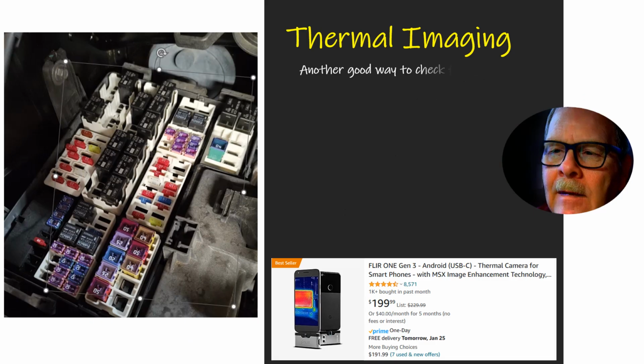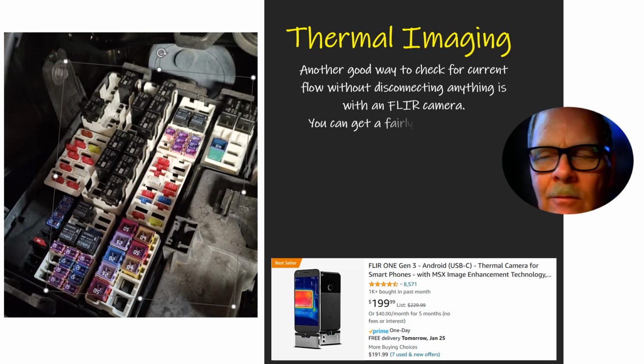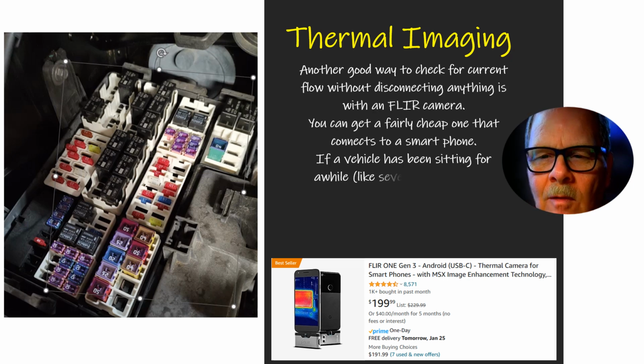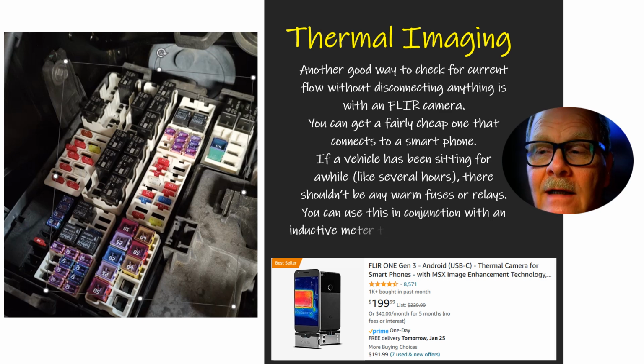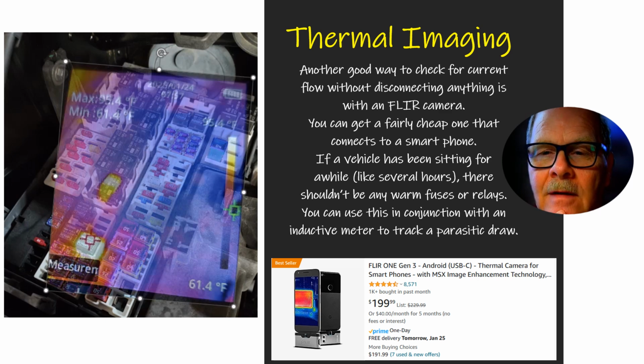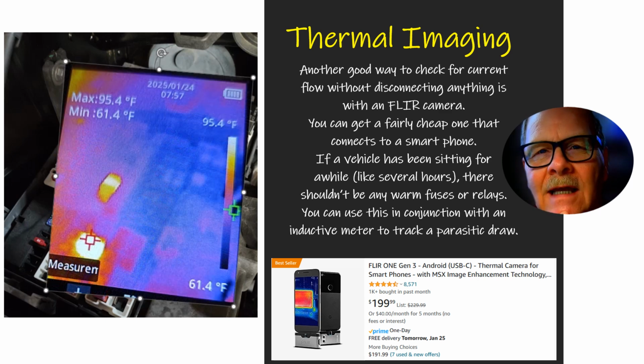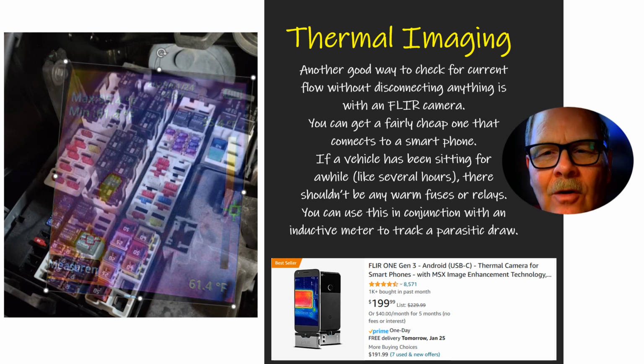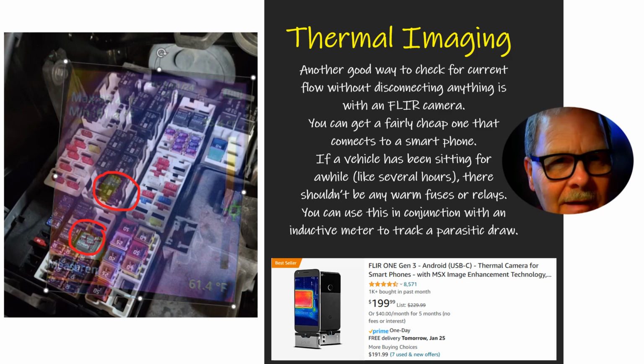Yeah. Anyway, so thermal imaging. Watch this video I just made this morning on my wife's pickup truck. All right, now. All right, watch this thermal imaging. I overlaid the thermal imaging. See the warm relays? Those warm relays are the ones that actually have current flowing through them. Now, interestingly enough, on this particular vehicle, that's not abnormal, but if you leave that vehicle parked too long, you can see how it would kill the battery.